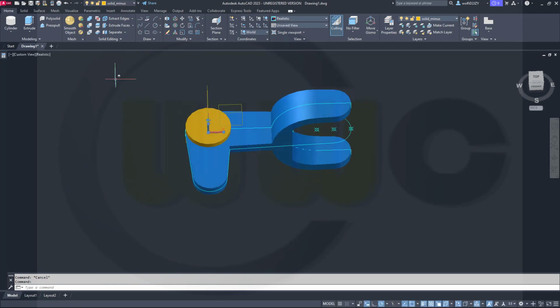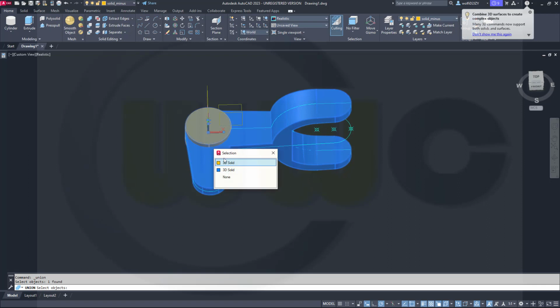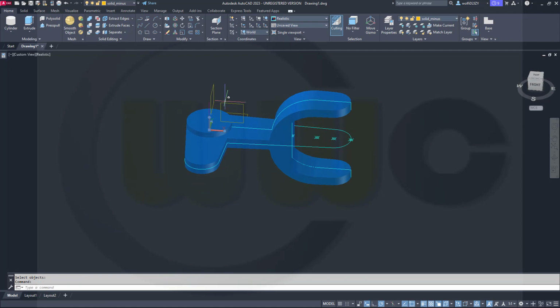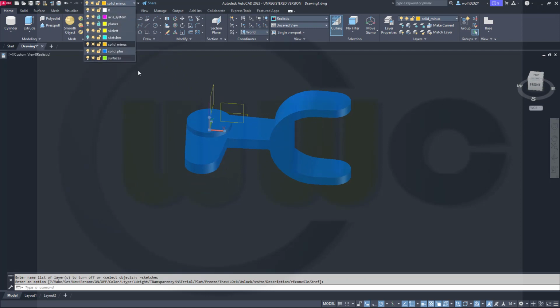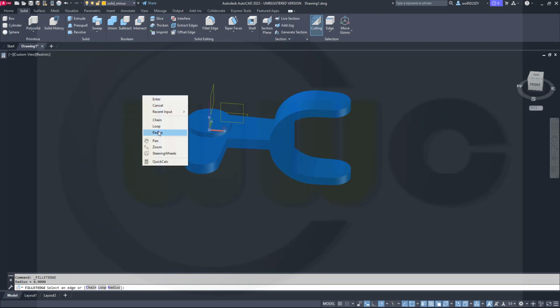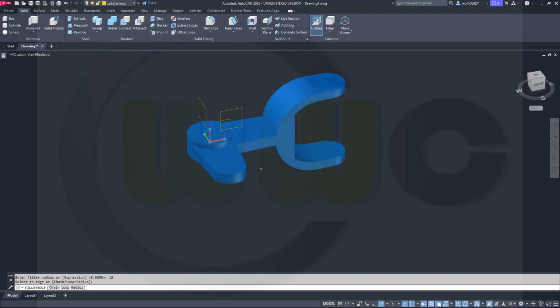And then make a union, so go for this solid, and that one should be combined. Great. Maybe hide those sketches. Then I can make my fillets. So go for fillet edge, start with a radius of 15 on this edge here, this one,